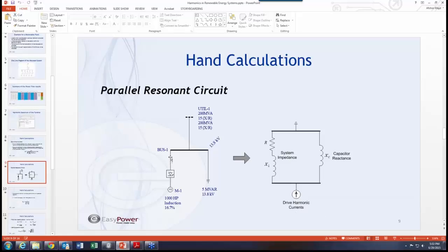I assume that ground and ground, so these and these are in parallel. It's basically just the equivalent circuit of what you see here. So R, X, XC. Now it becomes more clear that there might be a chance that at some frequency these two cancel each other out, and you would see a short here.